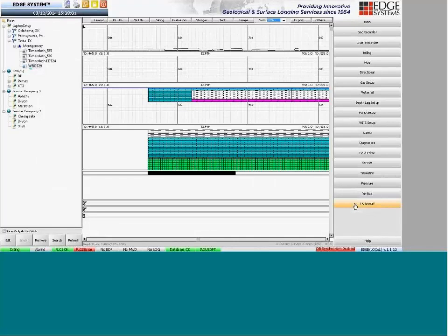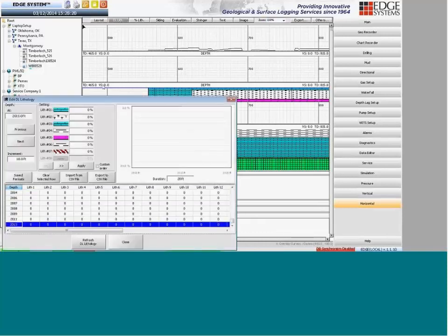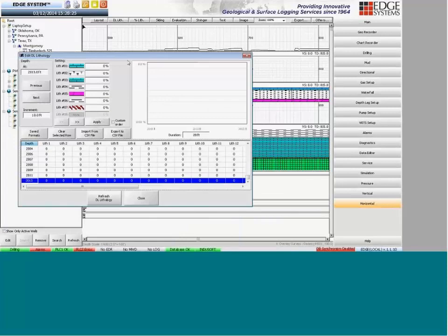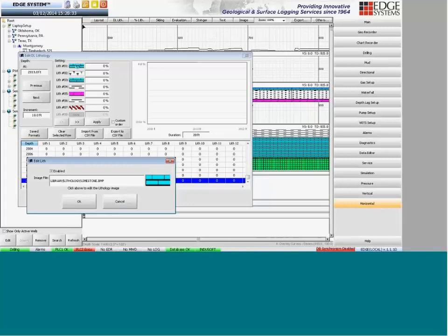And the product automatically fills the area below the pens with those pictures and tiles them side by side so it looks like a pattern. And each one of them is just a pen in an XY plot. Through the configuration screens, the engineer can select the different types of soils, which translate into particular pictures, JPEGs, PNGs, BMPs in the project, and define the coordinates for each one of the soils, which translates into how the pens should be plotted on the trend control.